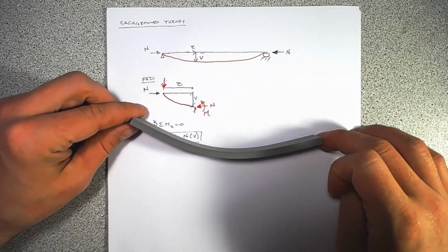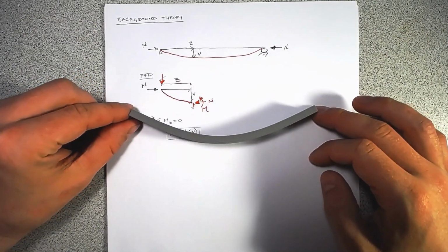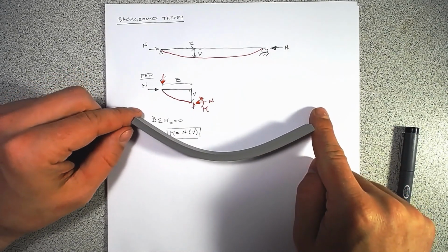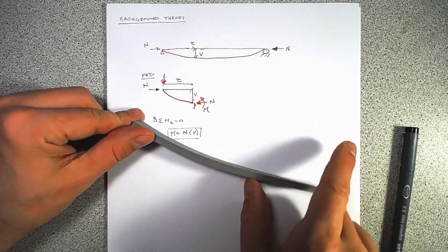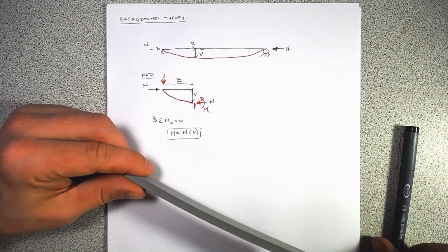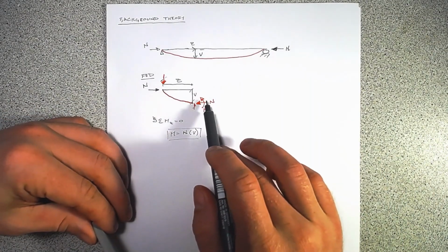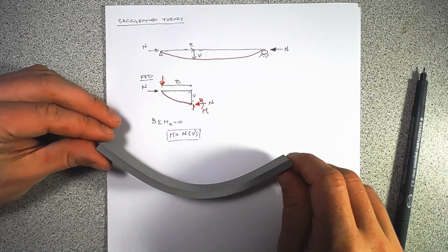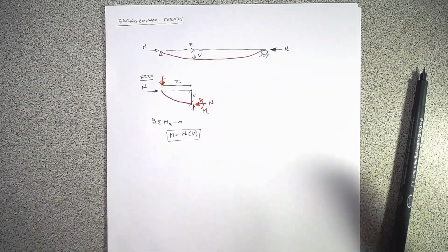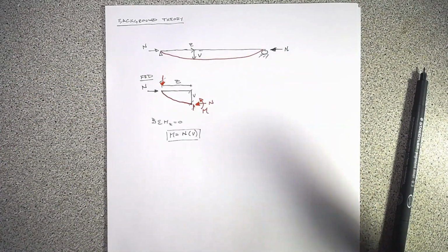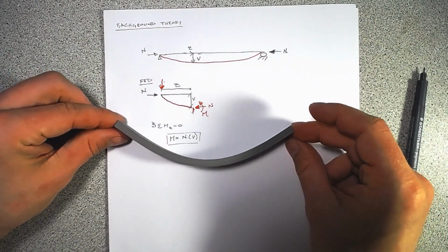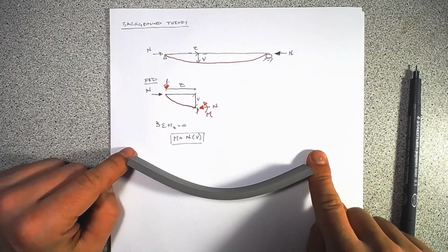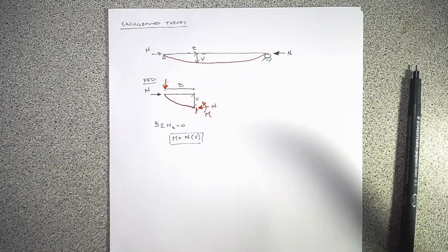The moment which is caused from buckling is really just going to be where this internal force is acting within the buckled member. So if we buckle this member here, we've got force running along the axis. Well, if we buckle it, it's now in a curve, and so you have a component in both the x and the y direction, which is what we're seeing here. And the moment that we're looking at is from the axial direction, and that's just going to be based upon the distance which this buckled shape is from the center line between the two points of support.